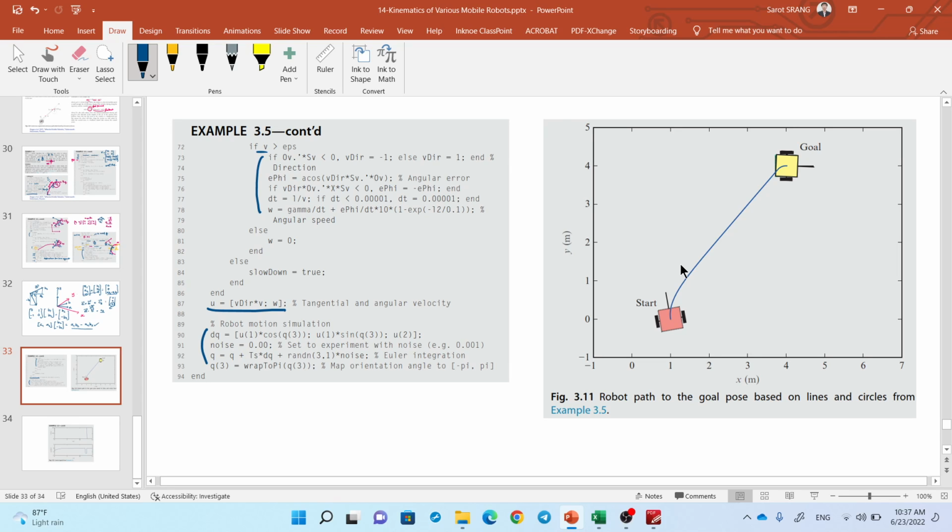So in order to simulate this algorithm, as long as you know the location of the robot, I mean the location x and y of the robot, and also the orientation phi, you can plot the robot body accordingly with these known parameters. This x, y, phi is computed by the last equation.